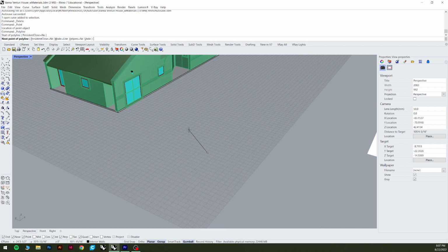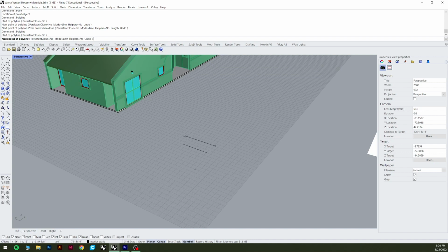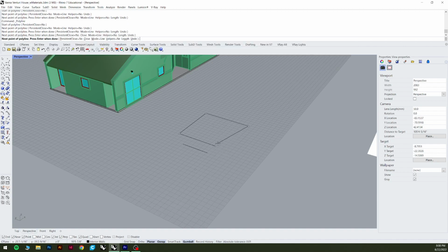Very useful in very specific situations. You can create lines. You're a line segment. You can use this polyline command in the same way and click once, but then continue to click, and you can hold shift to lock it into an orthogonal orientation. And then you can also return to the starting point of this polyline to create a closed shape.